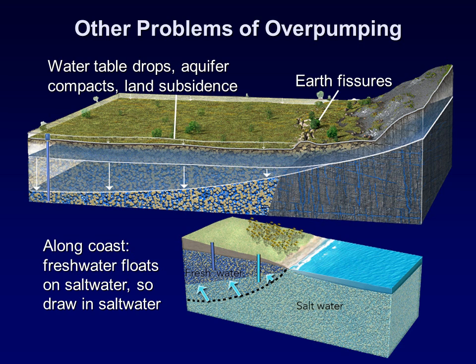And areas can drop meters to tens of meters in elevation when we're talking about subsidence. It's a really big deal, and to detect subsidence, they do repeated surveying with conventional surveying equipment, GPS, and other satellite measurements to measure the surface and see what its elevation is and how it's changing over time.